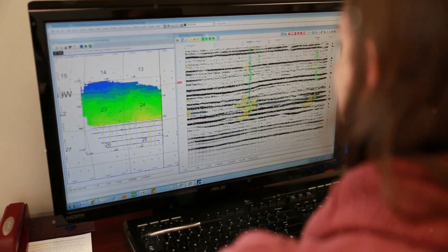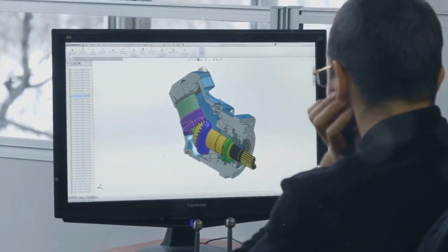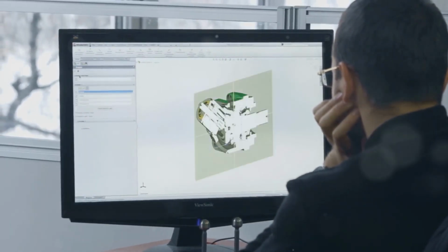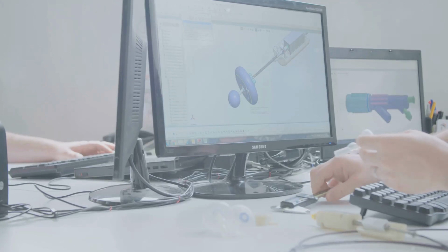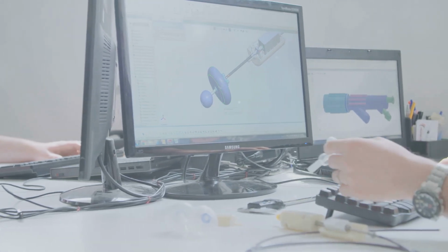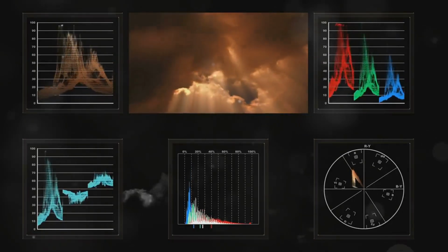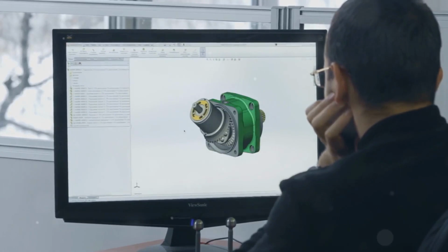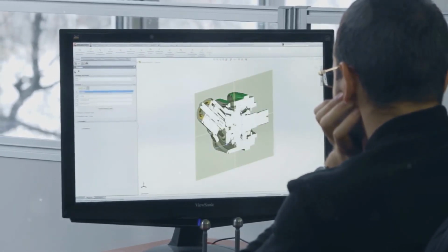Section 6. Achieving convergence and interpreting results. Convergence is the holy grail of FSI simulations, indicating that the solution has stabilized and accurately represents the physical behavior. However, achieving convergence can be a delicate dance, often requiring adjustments to the simulation setup and parameters. Several factors can influence convergence, including mesh quality, time step size, and convergence criteria. A well-defined mesh, an appropriate time step size, and tight convergence criteria are crucial for achieving reliable results.